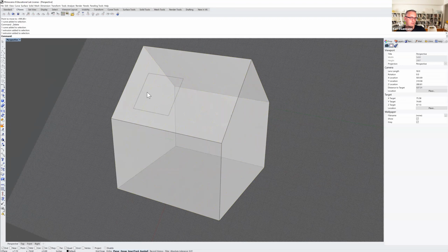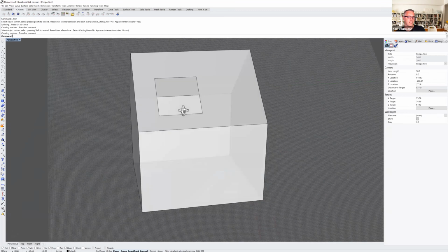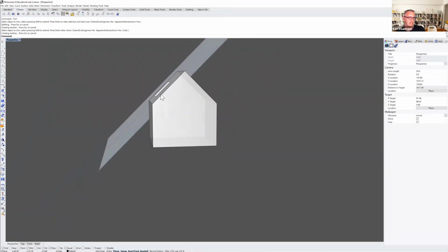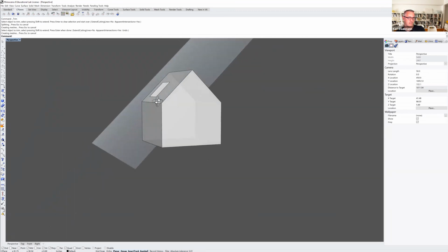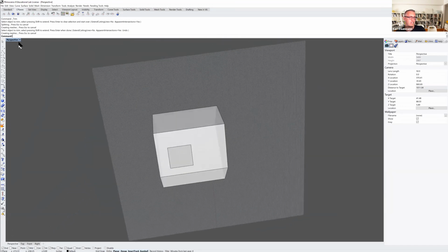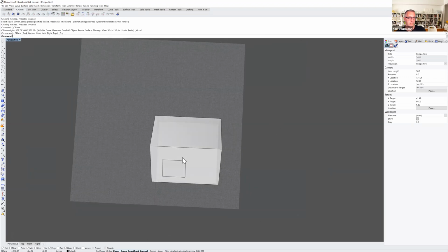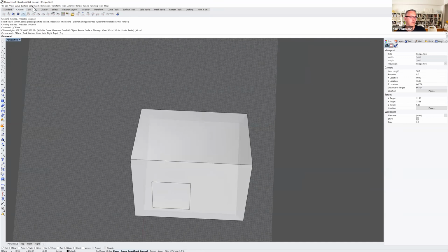I was going to say it's useful to see when we're trimming something. So we can trim, and then trim that hole out. So now we have that 4 foot by 4 foot skylight because we drew it directly on that surface and all of our dimensions were right. The difference would be if we tried to draw this from the top view and we drew on the other side a 4 foot by 4 foot skylight.